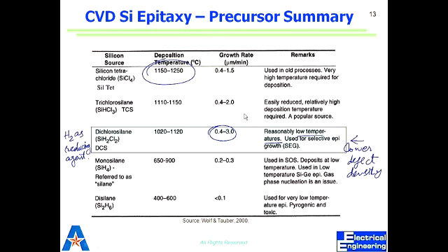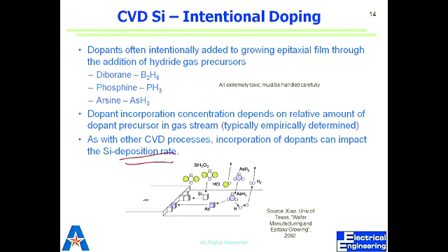So this one is the best, which gives you low defect density. That's why it's used for a process called selective epi growth. Selective epi growth is where we grow only at specific places, and we'll see how we do that. So if you have silicon dioxide and you make openings in it at specific places, in specific shapes, to reach silicon, your epi will occur only where the silicon is exposed, right? At the end, you can then etch your silicon dioxide away. So that's called SEG.